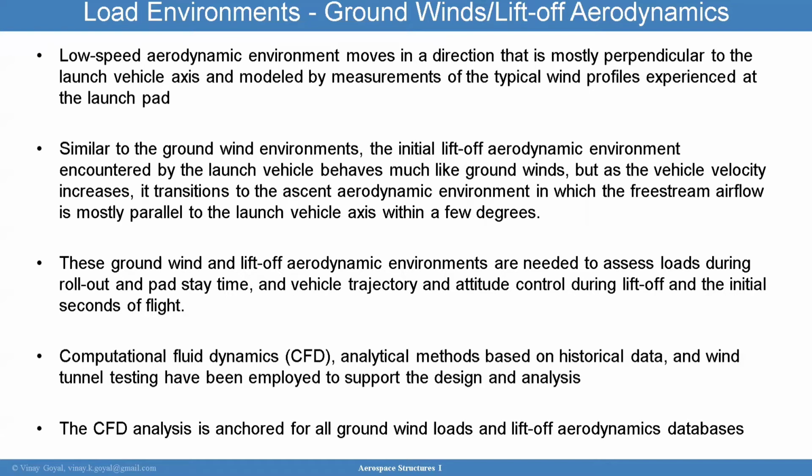These ground wind and liftoff aerodynamic environments need to be assessed during rollout and at the pad. And also at the vehicle, you have to look at vehicle trajectory and control during liftoff, and that's at the initial seconds of flight. You can use computational fluid dynamics and analytical methods based on historical data and wind tunnel testing to support the design and analysis. The CFD analysis is typically anchored for all ground winds and liftoff aerodynamic databases.